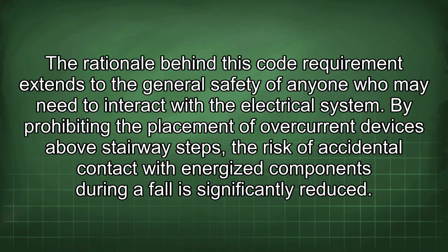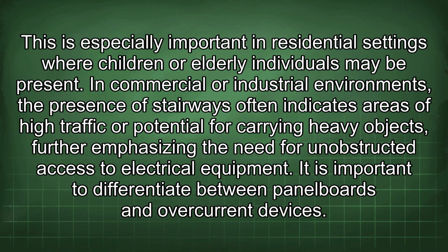The rationale behind this code requirement extends to the general safety of anyone who may need to interact with the electrical system. By prohibiting the placement of overcurrent devices above stairway steps, the risk of accidental contact with energized components during a fall is significantly reduced. This is especially important in residential settings where children or elderly individuals may be present. In commercial or industrial environments, the presence of stairways often indicates areas of high traffic or potential for carrying heavy objects, further emphasizing the need for unobstructed access to electrical equipment.